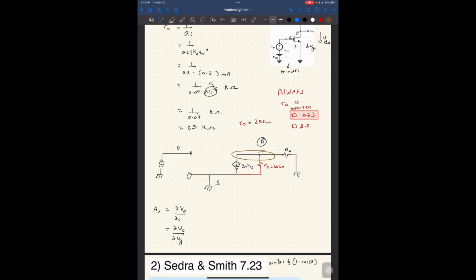or, you know what? No. Here, I understand that this is connected to ground. So r0 is between D and 0, and RD is between D and 0, meaning that I could technically redraw this in this format. And technically I could connect these two together because it's ground, which means that they are in parallel, no?